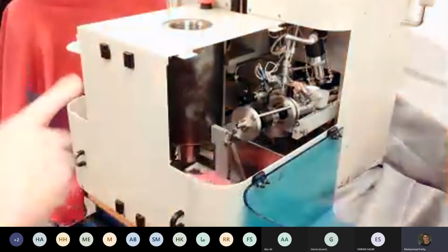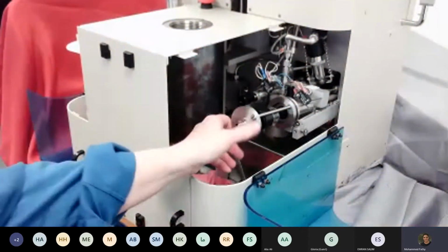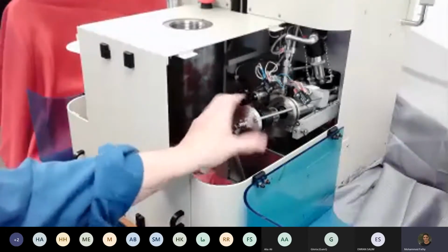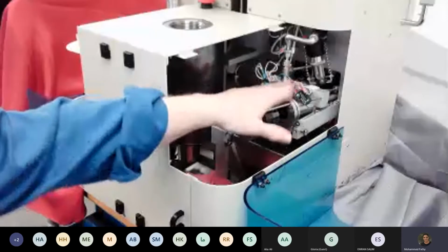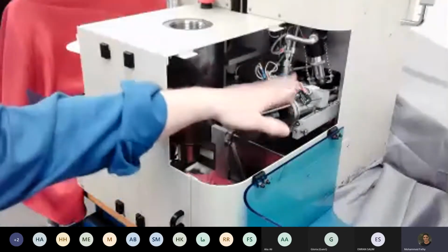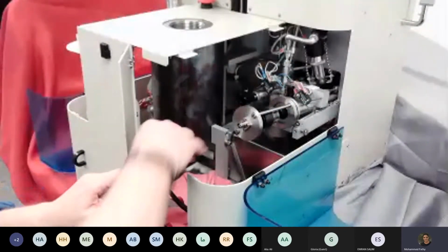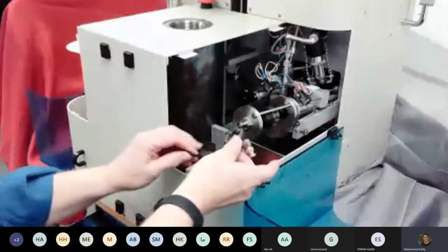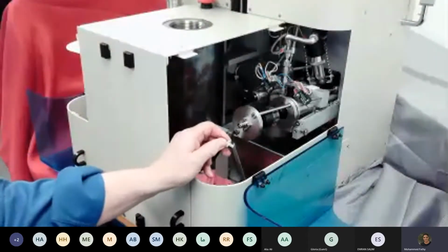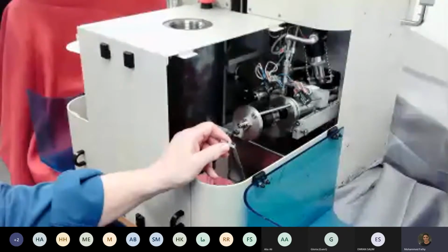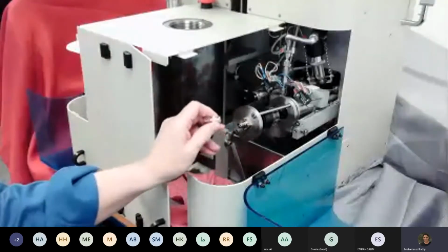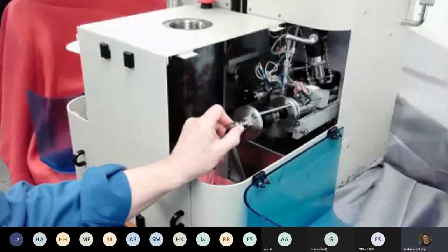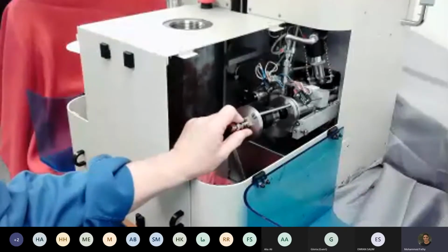So this assembly here holds the sample cell into the instrument, because don't forget, we're going to go to 3.5 bar here, and then if you remember, the mercury in the stem of the penetrometer is in contact with that metal plate on the penetrometer, which we call an electrode, and it forms part of an electrical circuit when I attach this,